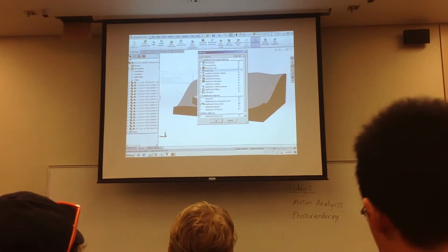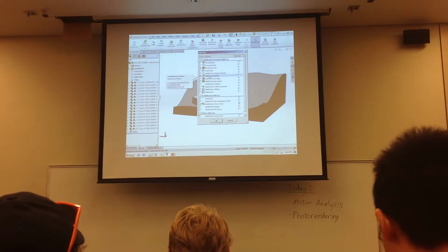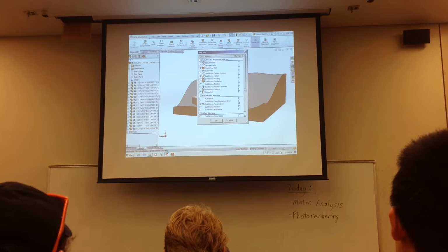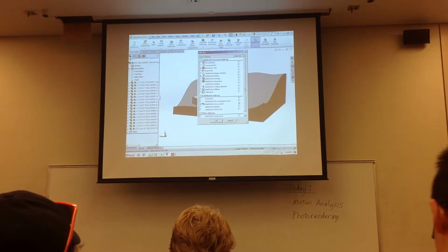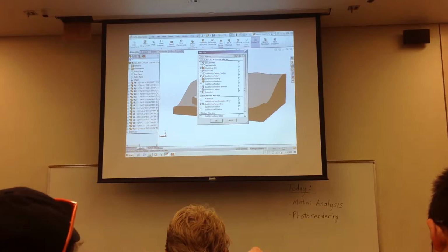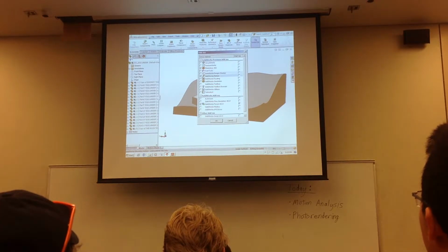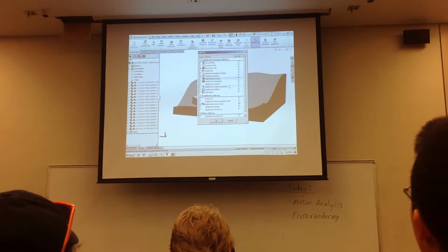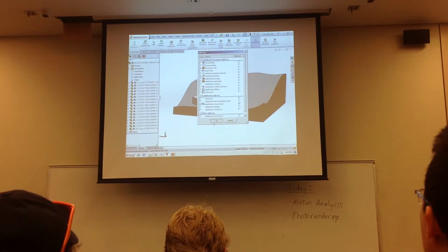So checking them on the left will add functionality to your current session of SolidWorks. If you check it on the right, it's going to load that functionality every time you start SolidWorks, which will make the time to load SolidWorks quite a bit longer. So generally it's better to just add them when you actually want to use them in a particular session. Don't choose to do them every time on startup. We'll accept that.